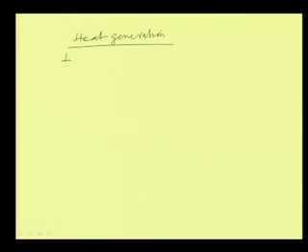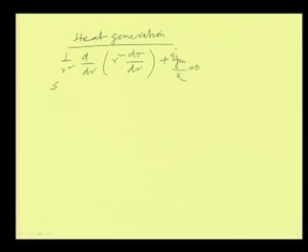We will get 1 by r square d dr of r square dT by dr, and that equation will be a little bit modified, as we have seen in the case of the cylindrical coordinate. This equation remains the same whether it is heat generation in a solid sphere or in a hollow sphere. For a solid sphere there will be a boundary condition difference, and if it is a hollow sphere, the boundary conditions will be changed.